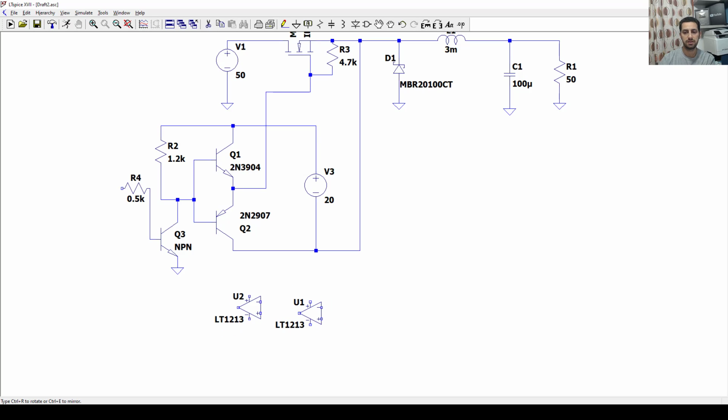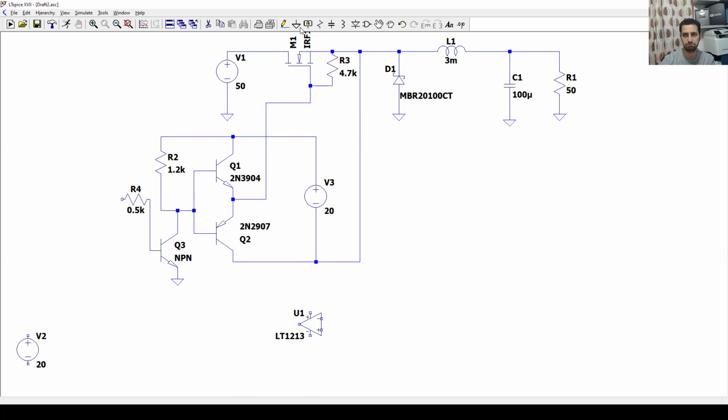Okay. And now we want supply. So from where to get supply, I will duplicate this voltage here and bring it there. And another will make a wire or ground like that, and wire. And then a net name, just to make sure that I want VCC.